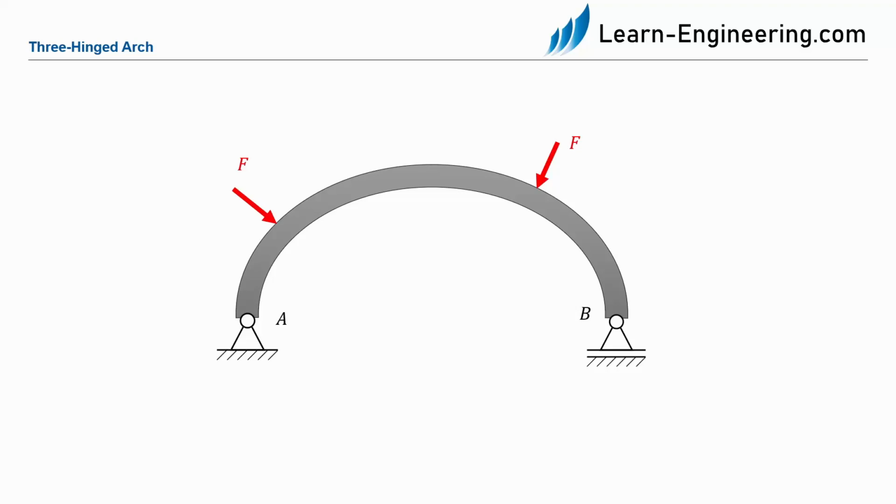Now, in the case of the rigid body, the body is thus optimally supported, but in reality that is not the case, because there are strength problems in the body, because the simple support can move further. So it is better to use a hinged support instead of the simple support. However, this leads to the fact that we now have 4 support reactions and are thus statically indeterminate.